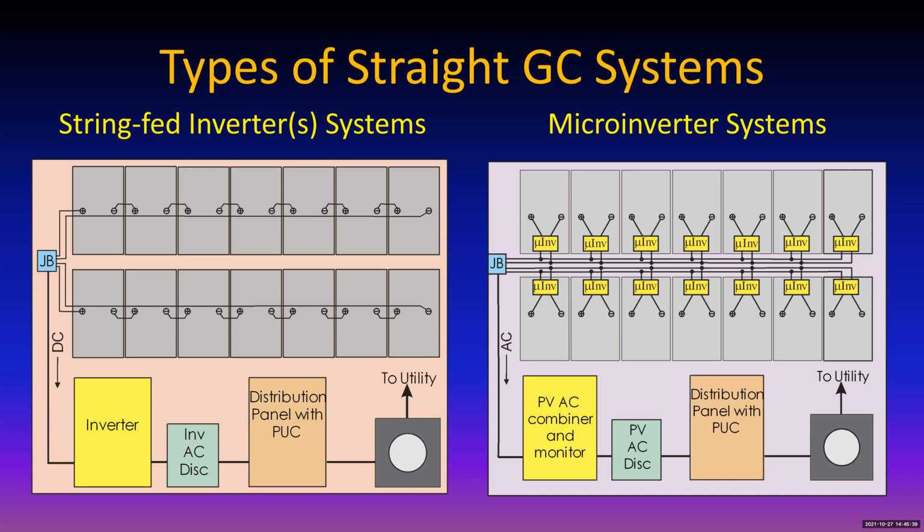Warranty on the microinverters now is the same as the warranty on the modules, 25 years. So pretty robust piece of equipment. Okay, and they're living underneath the modules, so they're shaded from the sun, pretty much shaded from rain, a reasonably desirable environment. So this is a microinverter system. The advantage being that every module is independent of every other module. It does its thing, and they all contribute whatever they can to the overall current on the line.